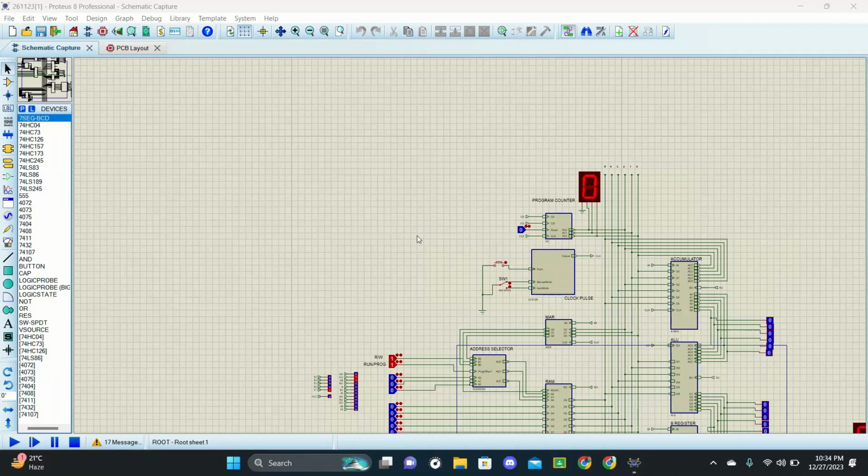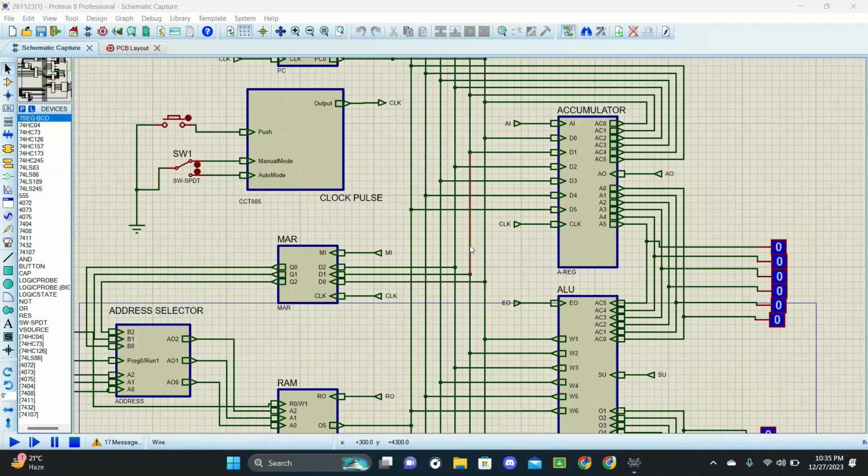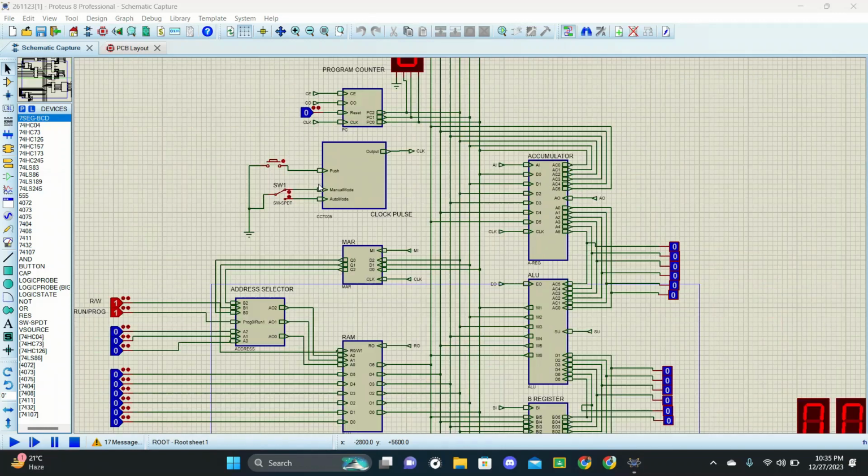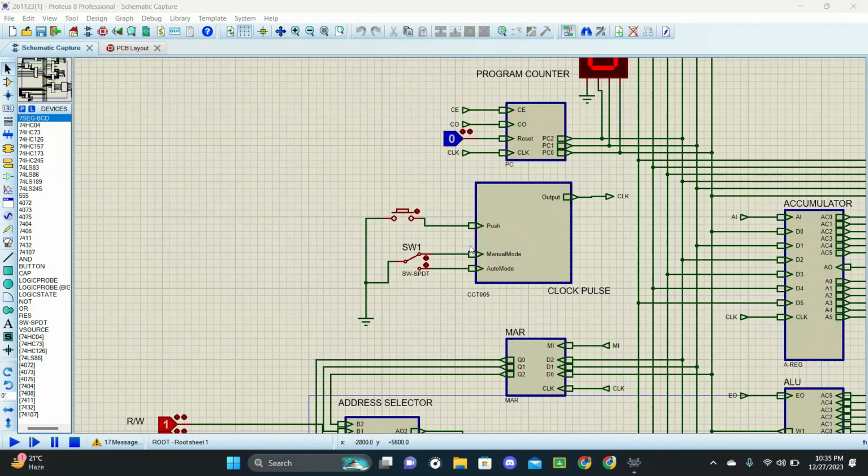In this video, I will demonstrate the SAP1 architecture-based 6-bit computer design and implementation project from Tripoli 4308. Here in this Proteus simulation, we have defined integrated types of modules with a 6-bit bus. At first, we have a clock pulse module, which will pulse from 1 to 0.